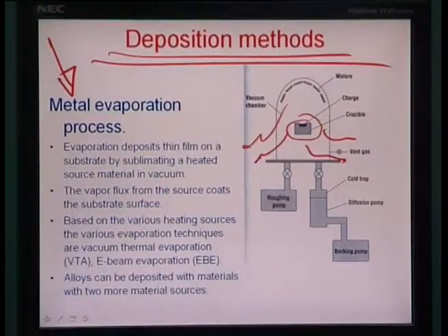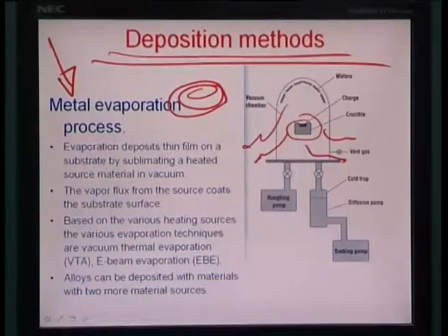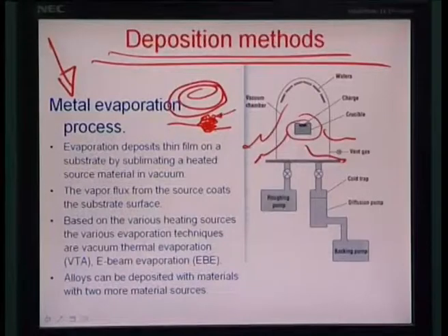So, this is actually a wafer holder or a wafer boat. Essentially it is made up of tungsten and something like this. If you look at the overall feature, it is something like a small boat like this on both sides, where your tungsten material is kept inside, the wire is kept inside, all folded and jumbled. Sorry, the material which you are trying to deposit is kept inside, and the tungsten has substantial resistivity, substantially lower temperature-based resistance variation, and can also withstand high temperature values because of its high melting point, which is about 3400 degrees Celsius.